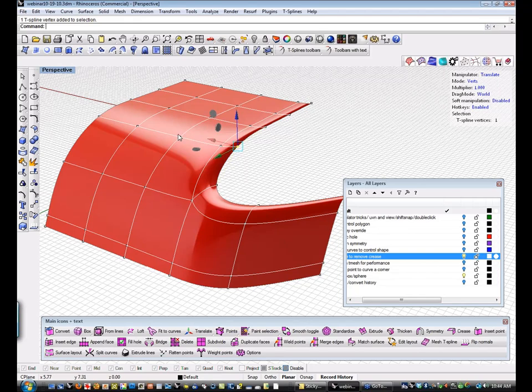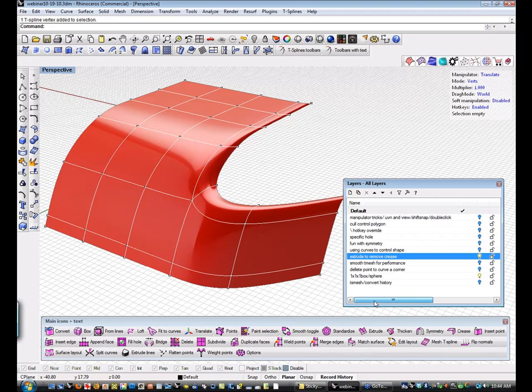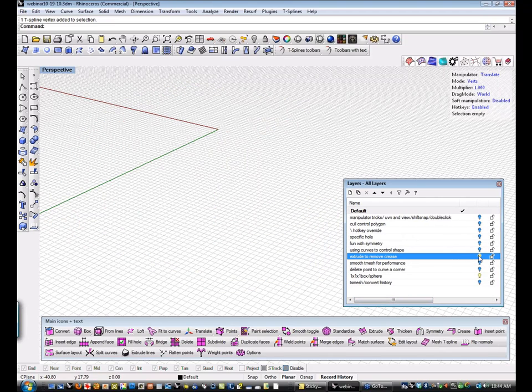If there was a stacked vert here and there was a problem in this area, I look up here. If it says there's only one vert, I know that's not the problem. If I go down here and it says there's two, that's your problem, weld there. That'll also fix issues with symmetry and some other common problems you can come up with.